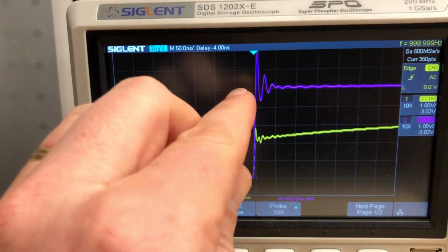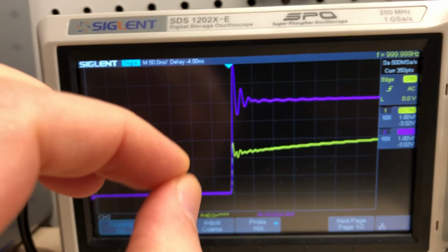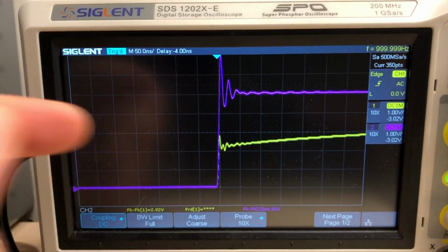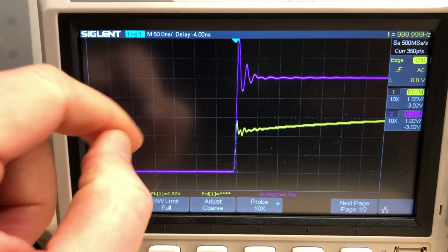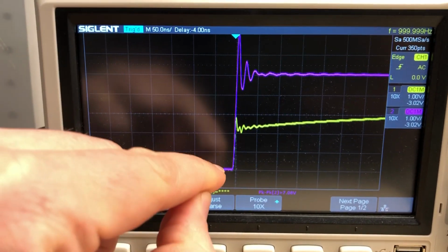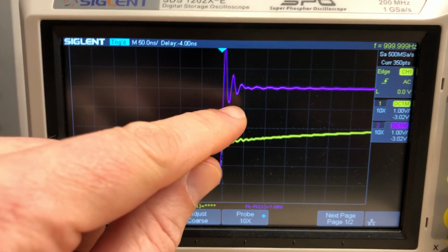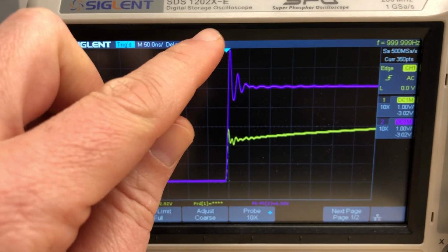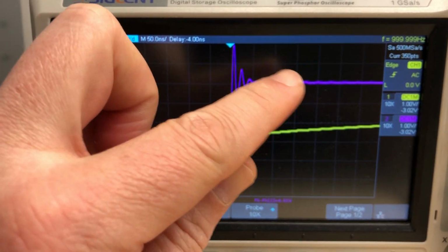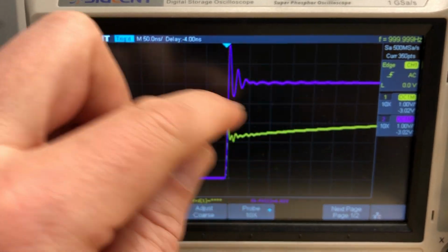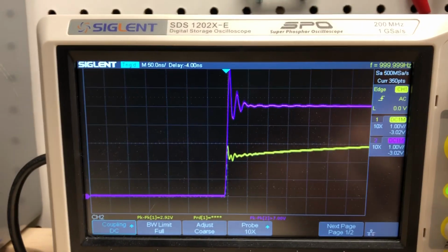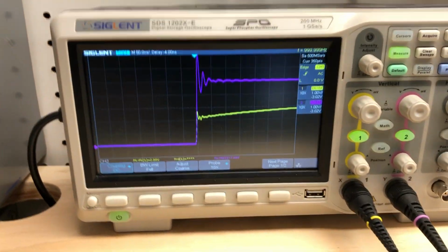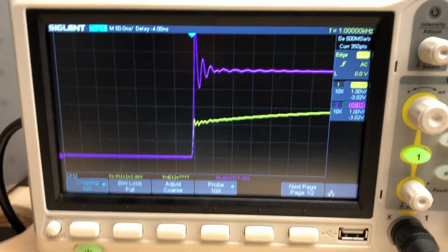So you're imparting that single shock which has a bunch of high frequency harmonics that are actually making up that super sharp edge. And this is, of course, exactly what's happening on the rheometer too. When you're imparting forces to a system, you can imagine jiggling a Haribo or another elastic system. You squeeze it suddenly, you impart the shock, it jiggles, and then that jiggling energy is lost as the energy is dissipated in this exponential envelope here. So once you start looking, you'll see ringing and overshooting and sine waves and exponents absolutely everywhere.